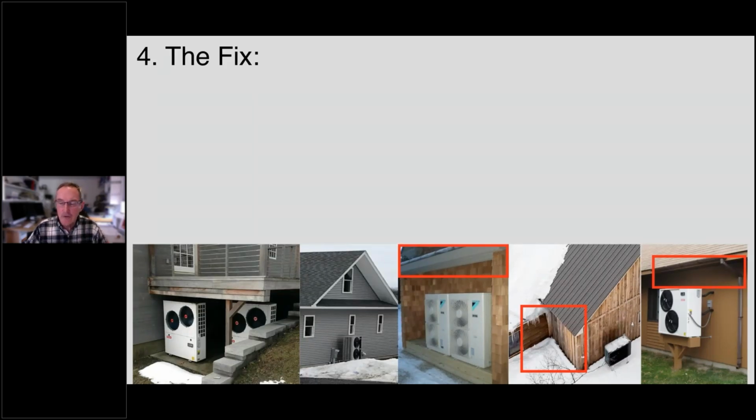And here's another photo. This is that elevated mounting, but you can see there's a gutter installed over this. It's a relatively steep roof, but it's a shingle roof. So typically snow doesn't slide, but rain will come down that roof. So there's a gutter that takes most of that rain and channels it away from falling on the heat pump.